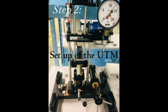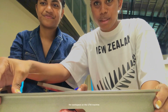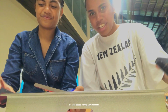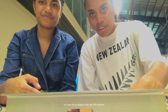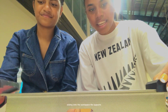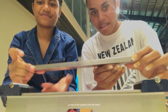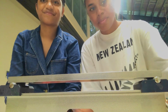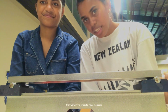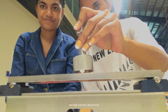Step 2. Setup of the UTM. It is set up by putting the workspace on the UTM machine. Like this, we fit the workspace onto the UTM machine, sliding the supports onto the workspace. On top of the supports was the beam, at a 300 millimeters distance. Then we turn the wheel to tighten the beam and make sure that it does not move.